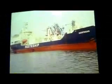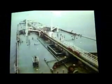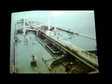These results apply only to a particular vessel and its associated class in Beaufort 7 conditions. For example, evidence suggests that some coastal tankers would drift downweather, stern or bow into wind. In the case of a smaller tanker, we would expect the drift speed to be higher. Some gas carriers show a high drift speed and a positive headway. It is clearly important to know the characteristics and response of your vessel in advance, should a breakdown occur.